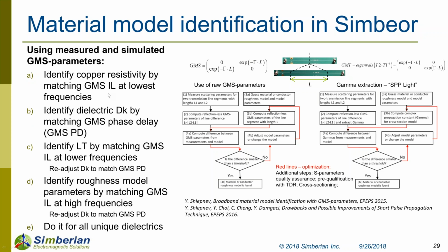First, using the lowest frequency, we identify resistivity by matching the lowest measured insertion loss. We used mechanical calibration kit measurements for this. Then we identified the dielectric constant by matching phase delay, and identified loss tangent using wideband bimodal. I'll talk about it later.